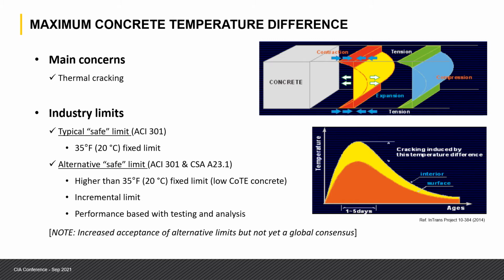In that case, you need to establish a fixed incremental limit that doesn't exceed 25 degrees Celsius. And sometimes you can use performance-based testing and analysis to show that the concrete can tolerate much higher temperature differentials, and they're qualified.